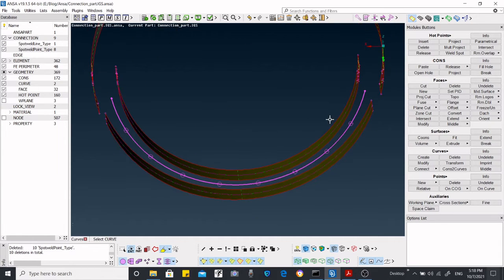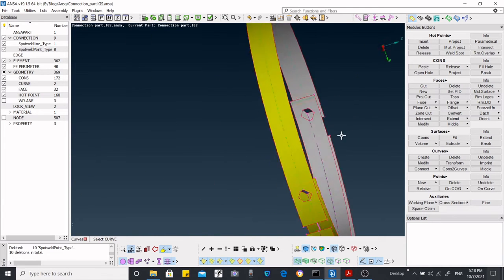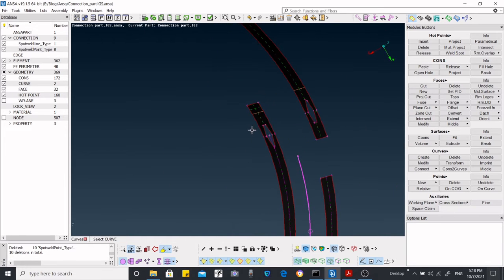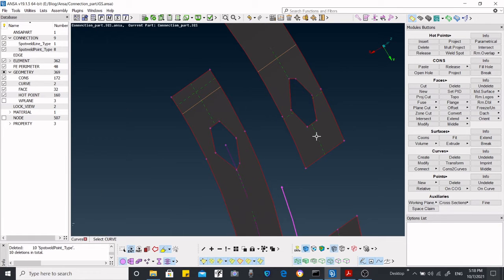Now the third thing that we are going to do is to create bolt connections. For the bolt connections, we need to create a line over here between these two. One more thing is that I want to remind you again that we are creating an FE model of the connections without using any mesh, right? So we are just using the surface. In another part we will see how to make an FE model and much more FE models which are really incompatible with the faces or surfaces. Okay.